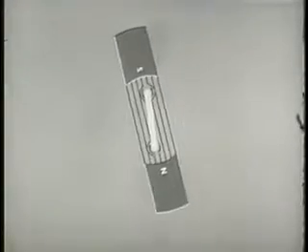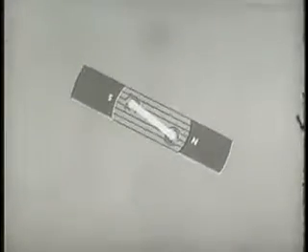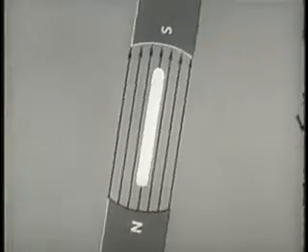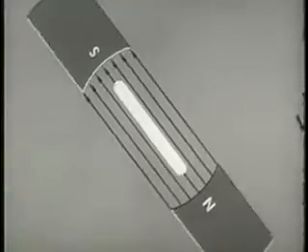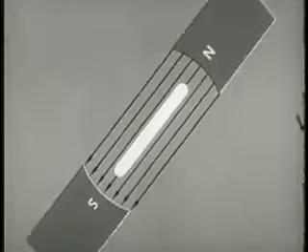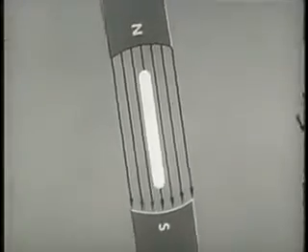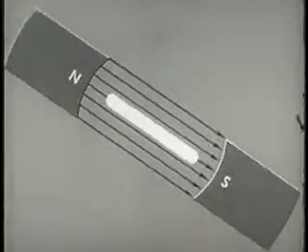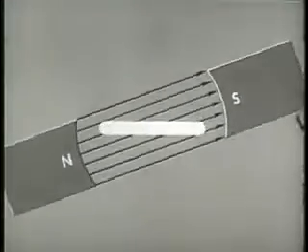The interaction between the conductor fields due to relative motion and the rotating magnetic field causes the rotor to move, but at a slower pace than the rotating field. If the speed of the rotor and the field were the same, there would be no induced EMF. No lines of force would be cut and no field built around the conductor. Obviously, there can be no motor action under those conditions.